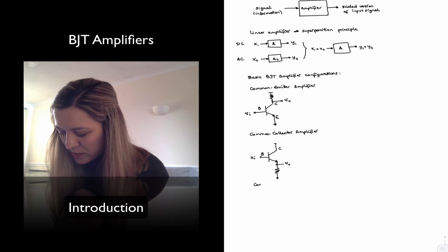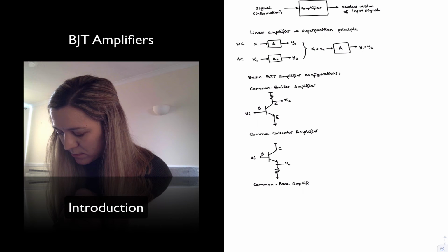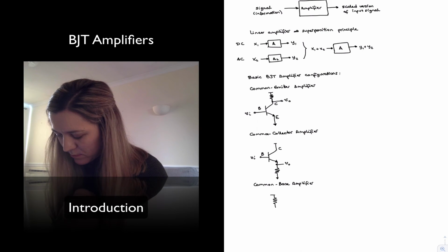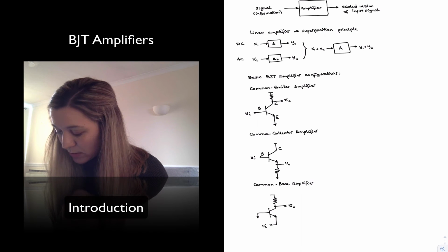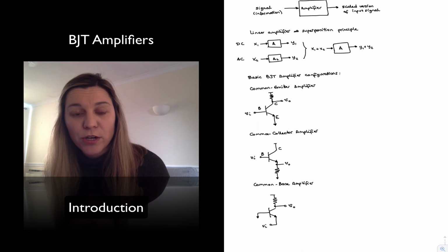And for the common base amplifier, the base is the common terminal, the input is applied to the emitter, and the output is taken out of the collector. So those are the three single transistor amplifiers.